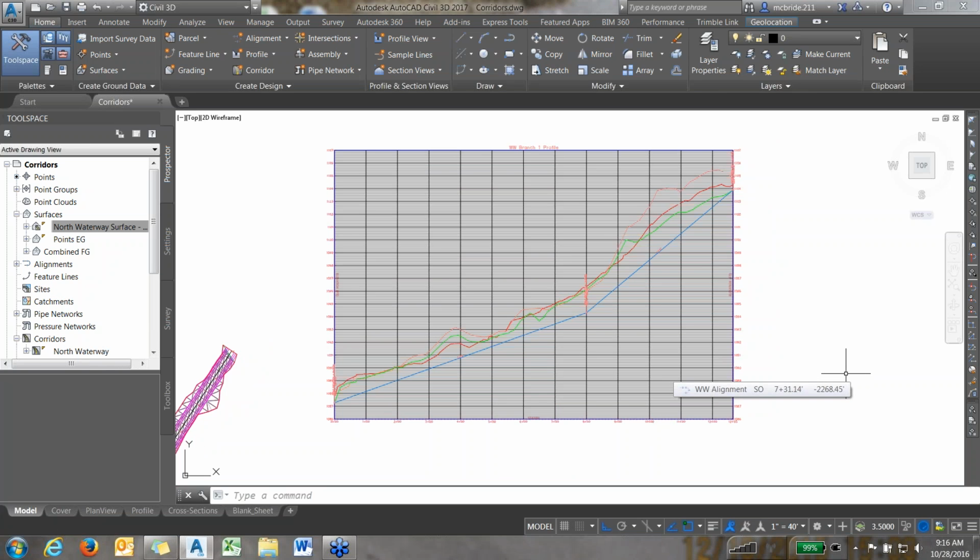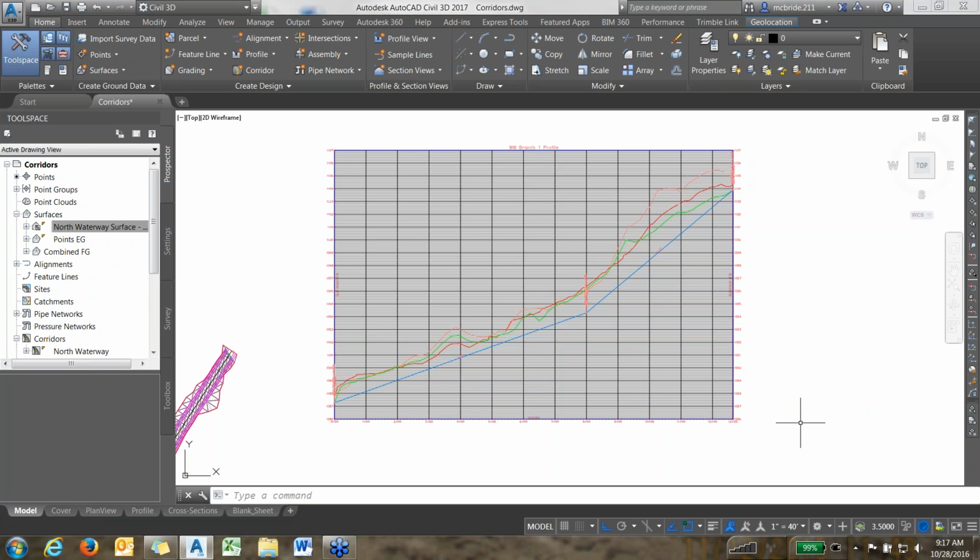No, but you have one question right off the get-go here. Could you run cut and fill numbers with this added surface and corridor? Yes, you can. And whether to use the combined surface or the corridor surface, I do not have a better answer which one's better. So I assume they should give you the same answer. We have not talked about how to find quantities yet as far as earth fills and cuts. We'll do that in the next webinar where we talk about cross sections.